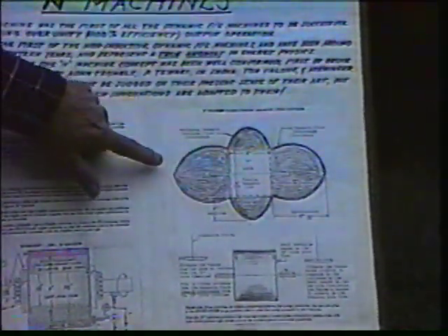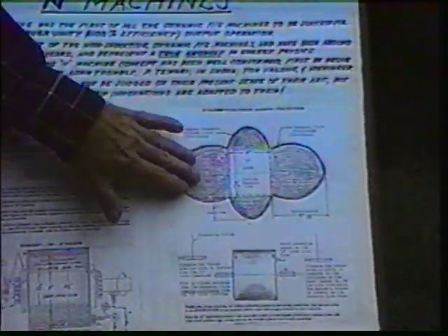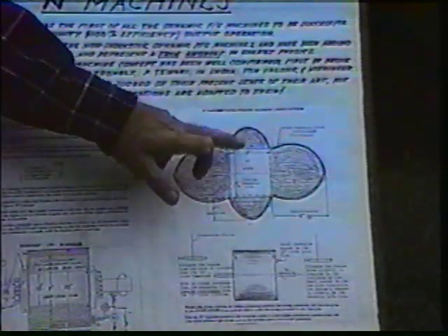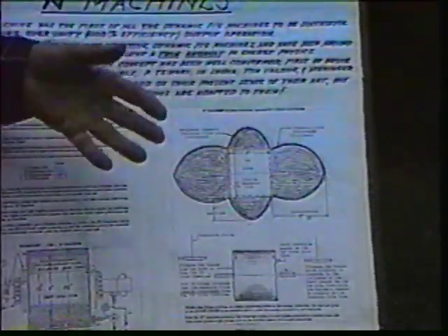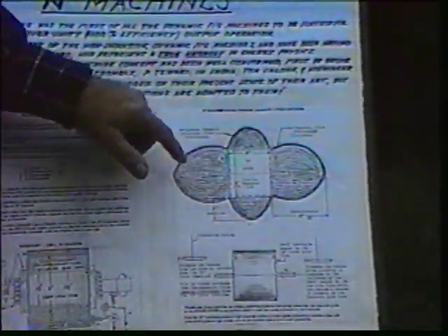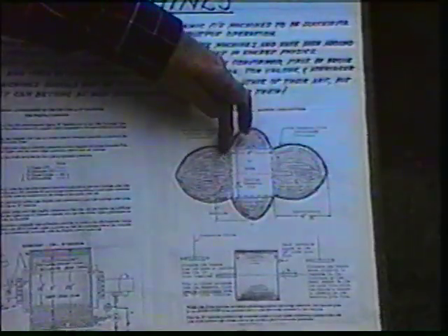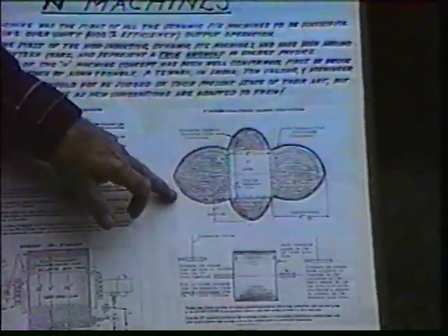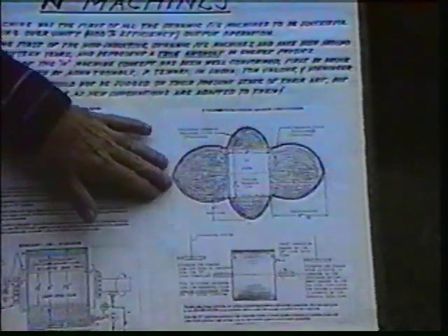But the most remarkable thing about these magnetic flux patterns is they remain absolutely stationary as that rotor revolves, which was an amazing thing to me because I just naturally assumed that the magnetic flux is revolving with the rotor, but it's not so. It doesn't. Now, I haven't explored this fully, there may be a boundary layer that does drag and revolve with the rotor, but the essential pattern, the bulk of the pattern does not revolve. It's absolutely stationary, which was amazing to me.